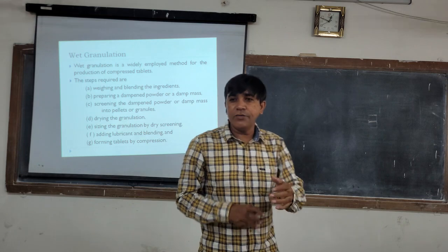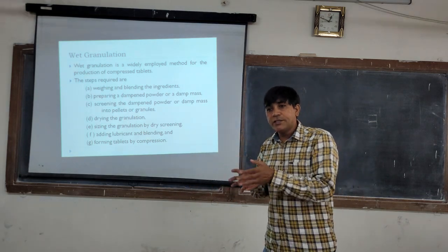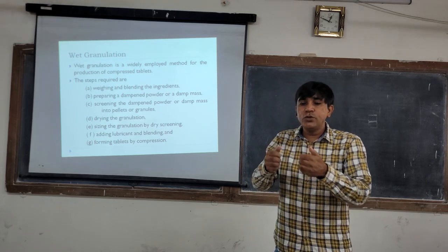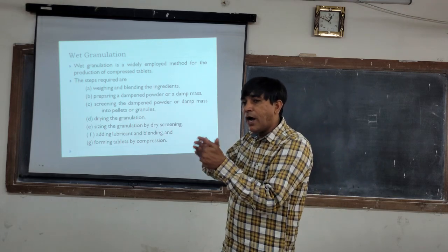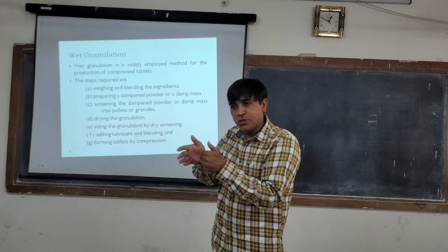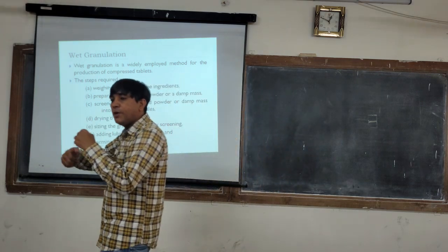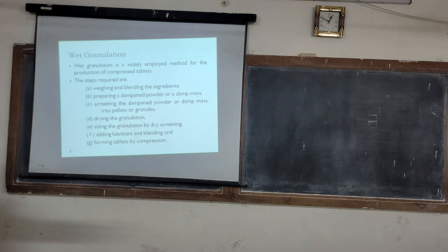Now, the granule itself is prepared by wet processing, and that is why it has good binding. But when two granules are compressed together, when they join together, they should have a higher amount of binder, and that is available with wet granulation. So this binder-rich surface will help in preparing tablets with good compression strength, good crushing strength. These are the steps involved in the wet granulation process.